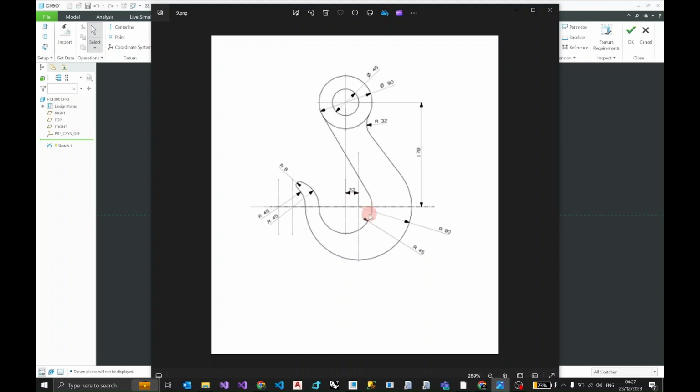First thing you can notice over here is that these two arcs and this one have a radius of 45 units or millimeters. Since this drawing doesn't have any mention of the units, we're gonna assume that it's millimeters. So this is 45 millimeters, this is 90 millimeters, and we can create two circles, with the inner circle center at the origin, and the outer ones a bit offset in the horizontal with a spacing of 22 millimeters. So we can do it over here.